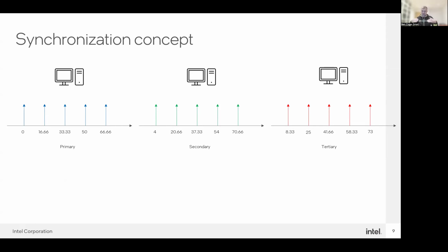So each one of them would have an HDMI output, but in very small fractions, they have a slightly different understanding of what, for example, 59.94 hertz is, and the clock associated with that. So you can't guarantee each of their understanding of 59.94 is the same because they have slightly different crystals and so on.